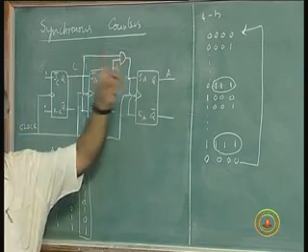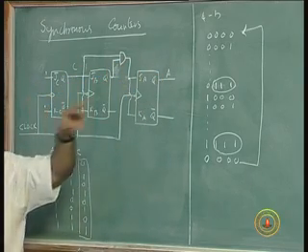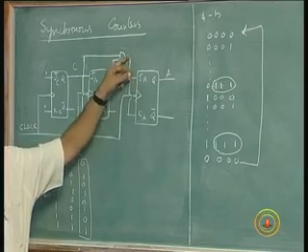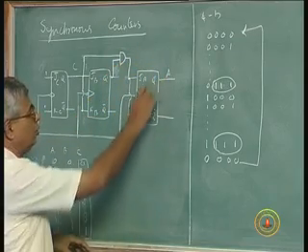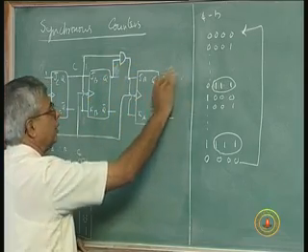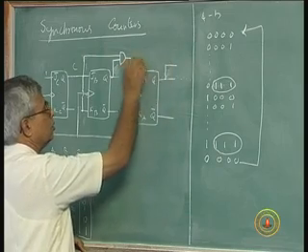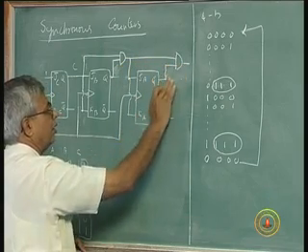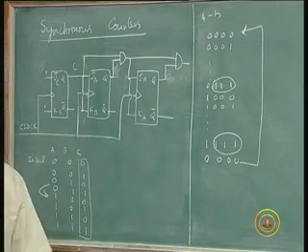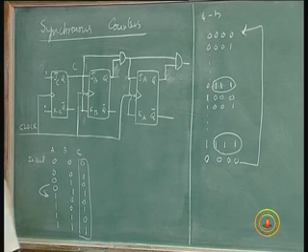So, every time I put a 2 input AND gate, taking the output from the previous AND gate as one input, and then if you want to continue, it will be like this. Isn't that so? I do not have to go for 3 input AND gates or 4 input AND gates. 2 input AND gates will do for each stage.